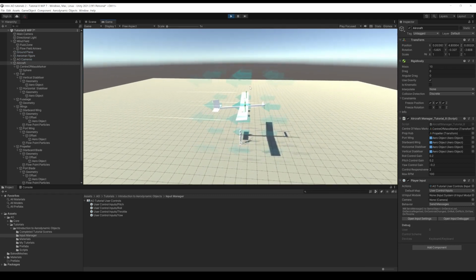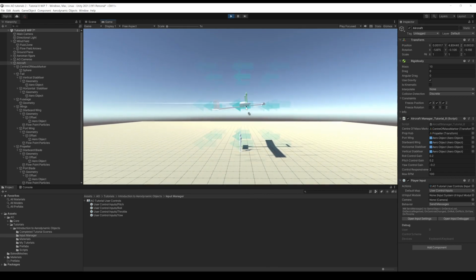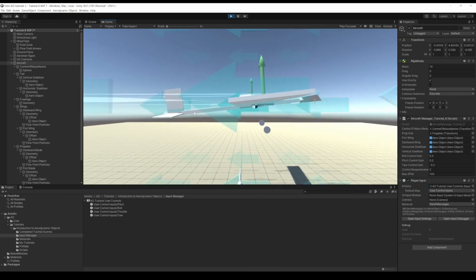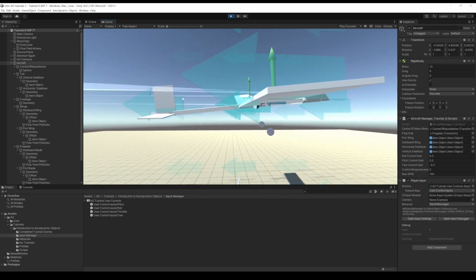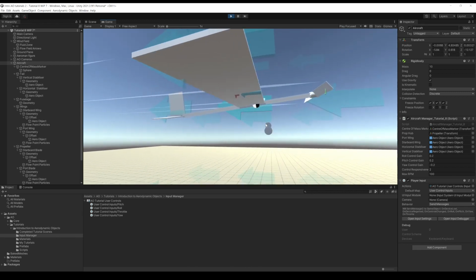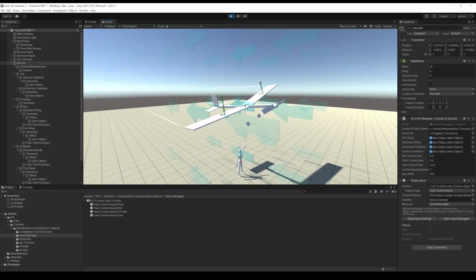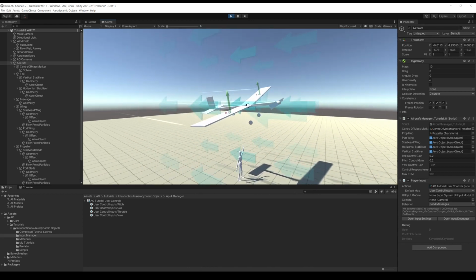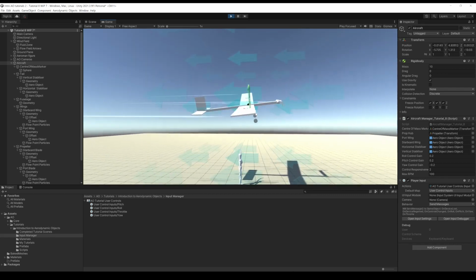Okay, so immediately what you see there is the aircraft, as soon as we let it go, has gone to a positive angle of attack, and that's because we have this setting on the tail plane with the leading edge down. What that means is it's effectively pushing the tail down, so this thing balances at a positive angle of attack, and that looks quite happy in the sense it's got lift on, and there's no control inputs, but it's got some positive lift on each of the wings, so that means it'd be quite happy flying.